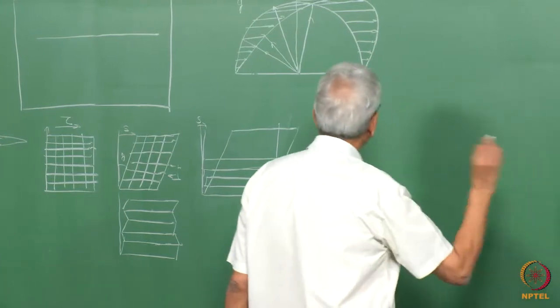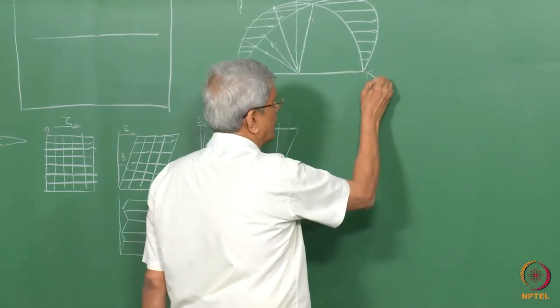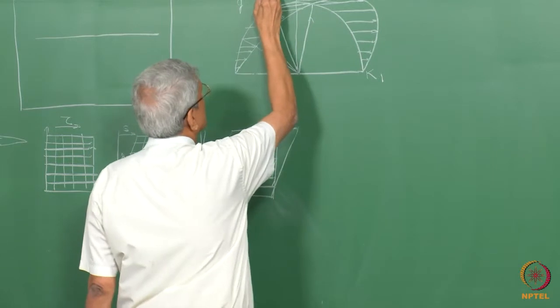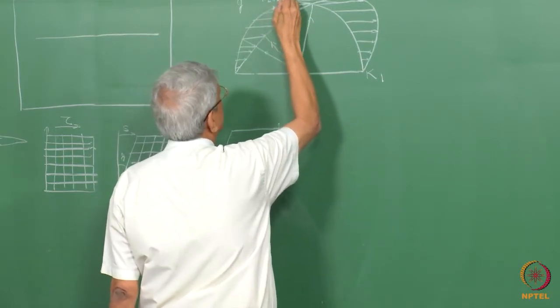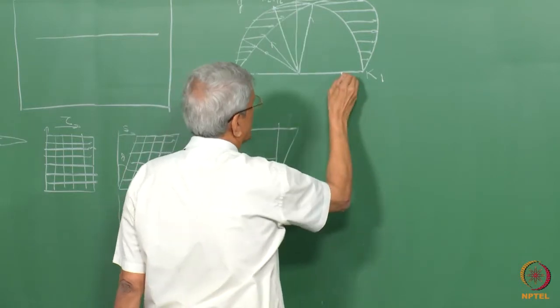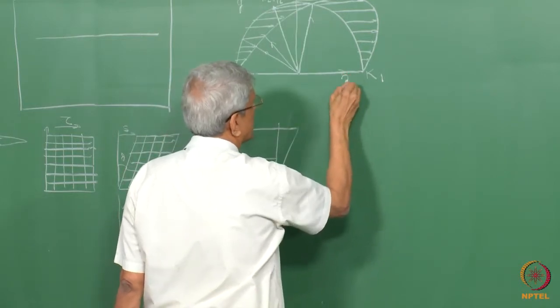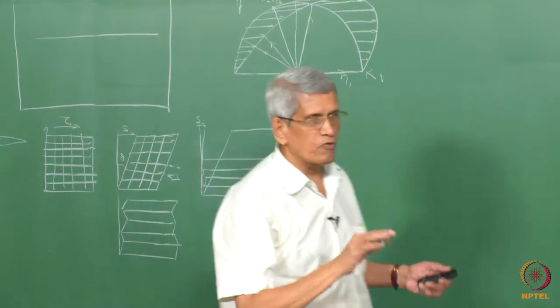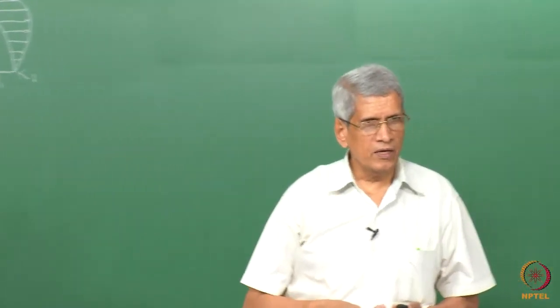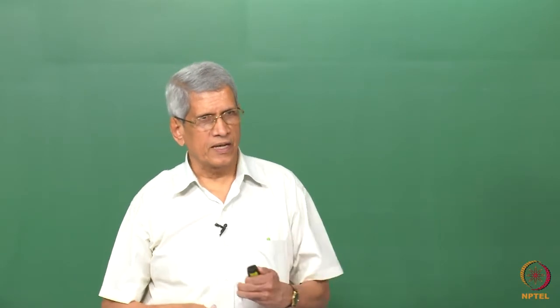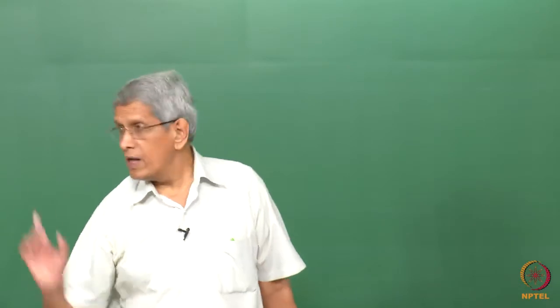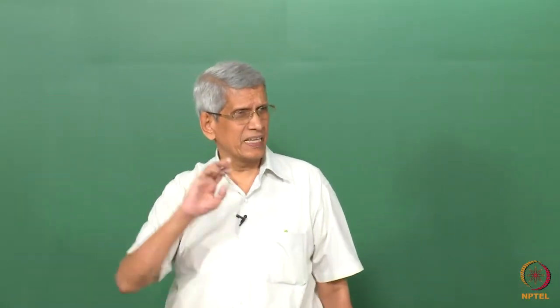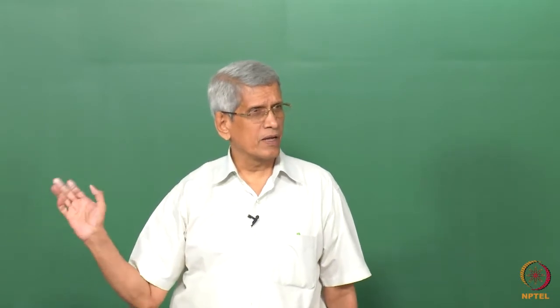This plane in twinning morphology we call as the K1 plane. The plane which contains here is called the K2 plane. This direction is called eta 2. The direction here is called eta 1. This you are familiar with. Recently only we have had lectures on these aspects, correct? So this is one characteristic, that is the plane gets rotated or distorted.